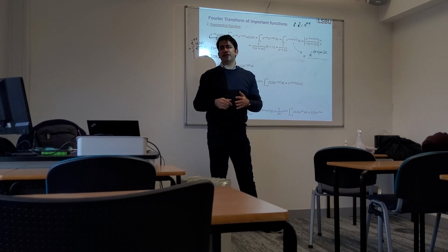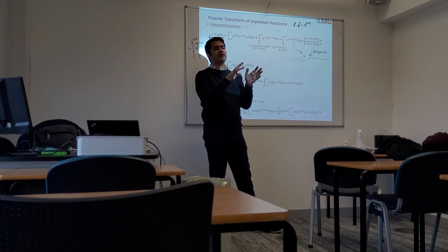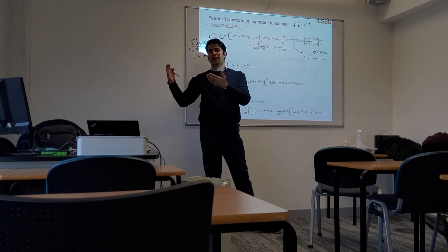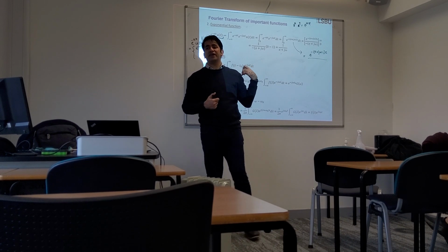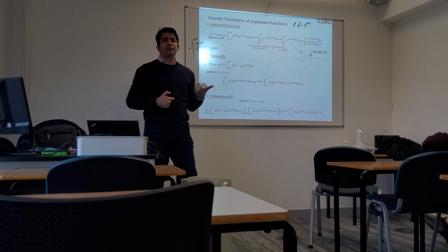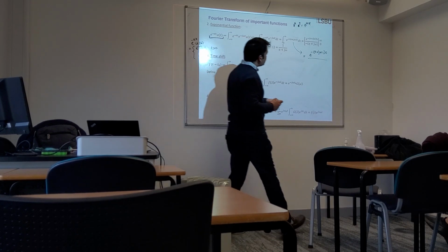In case of Fourier series, we always take the integral with respect to omega t. Why? Because we say that sine waves are repeating between 0, pi, and 2 pi, so it's easier to solve the integral with respect to omega t. However, in case of Fourier transform, since it is for aperiodic signal, we don't need to worry about period, so that's why we stay in the time domain.